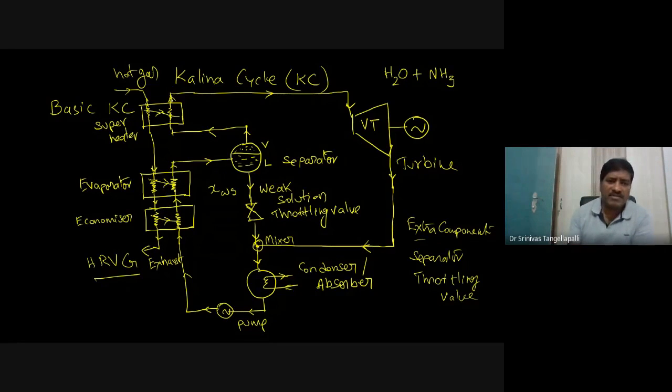So in the Rankine cycle, in the evaporator the working fluid is evaporating at a constant temperature. But in this Kalina cycle, since two fluids have been mixed together, the working fluid temperature is increasing in the evaporator. From the start it is at the bubble point temperature, but the evaporation is incomplete and it stops to collect the vapor and the liquid. So the temperature at the exit of this evaporator is below the dew point temperature of the working fluid at that particular pressure. So I'm using some terminology such as bubble point temperature, dew point temperature, and mixture properties.